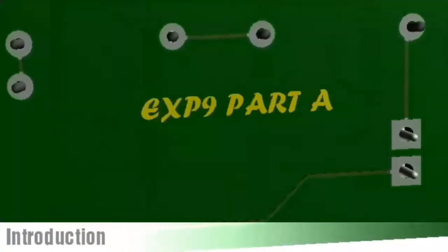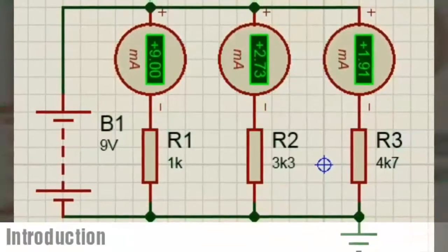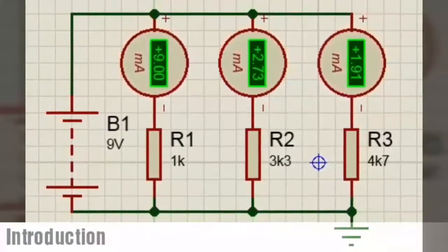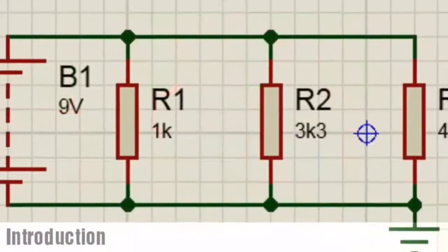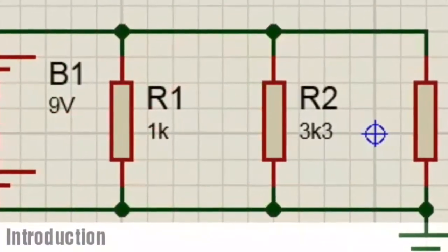Experiment 10 consists of 8 major tasks, which are board preparation, laminate process, exposure, developing, etching, photoresist stripping, drilling, and soldering. Next video is the procedure.